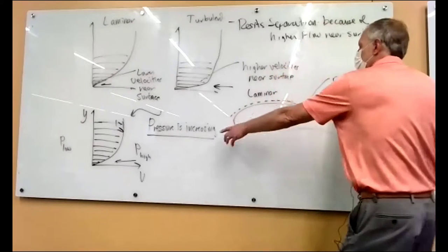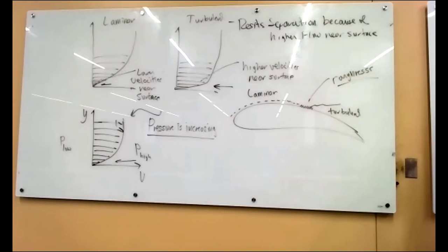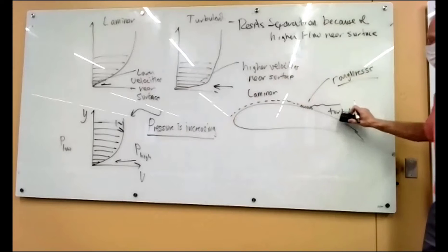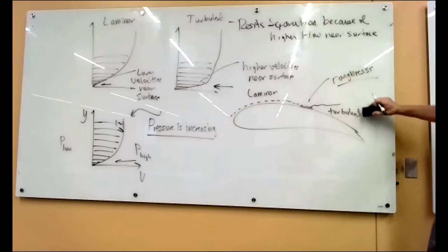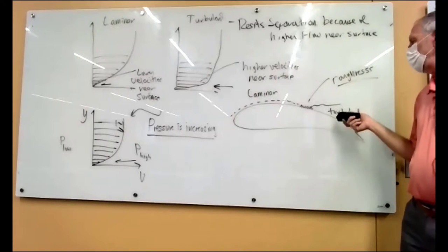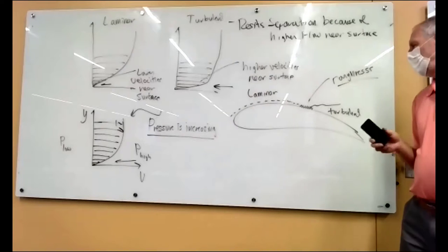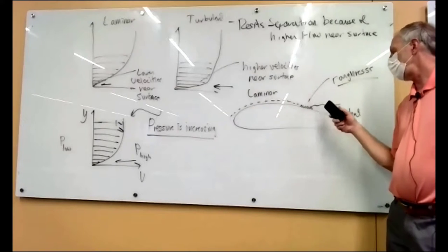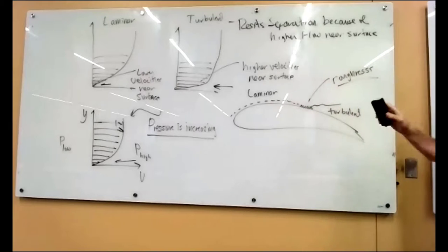And so you get laminar flow over a large part of the wing that gives you the low drag, so you're good there. But yet you get a turbulent boundary layer over the last fourth or so that then keeps this from separating, and it resists separation more. And you get less stall of the wing, and the whole wing doesn't stall at once. So that's how they get the best of both worlds. Wings are designed to trip. If they don't automatically trip due to their roughness, like the rivets and stuff in it, they will deliberately put something on here.